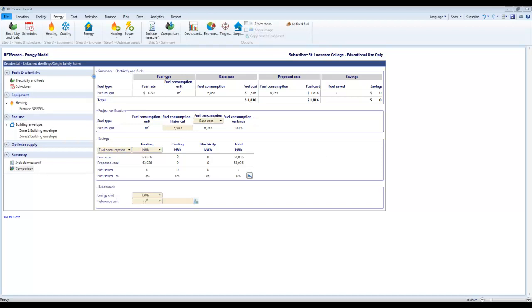So I'm going to conclude this video here and provide more videos with details of some of the things like how to model the R values. This is an overall picture and a first look at building energy modeling. As I said before, the most common mistakes that people make in RETScreen are to get the units wrong. So if you're getting very wild numbers that are not believable, go check your units.